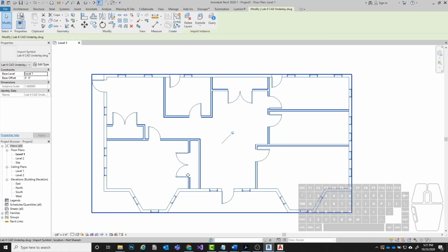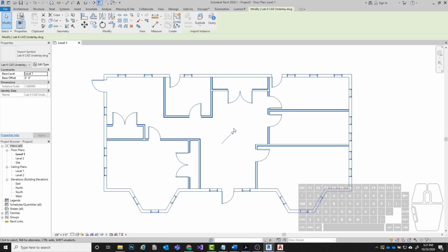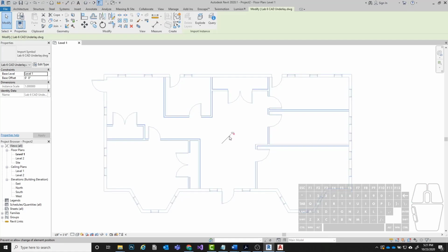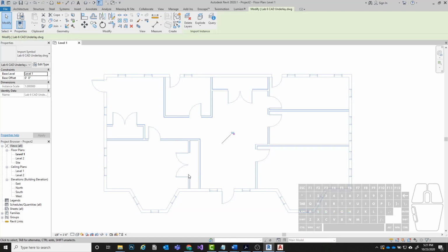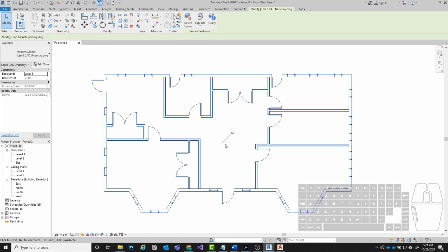So first of all, what I want to point out here is when you click on this, you'll see this little, this is what's known as a pin. You're actually seeing the top of a thumbtack. If you think of a thumbtack on a tack board, you're seeing the top view of a thumbtack. And if you were to click on that, now you can see the side view of it. The side view with the little X here is telling me that this object is not pinned in place. So literally just think of this as I'm using a thumbtack and I'm pinning a piece of paper to a tack board. When I tack it on, I can't move it. If I were to tack that back on, you can see now it's tacked into it.